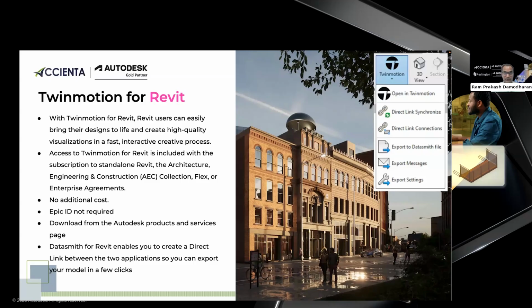So for example, if you're using it, Cholin, you can correct me because you are the power user who uses Twinmotion, and I just have some insights from you. That's my real experience, which I discovered: when I use Revit 2024, Twinmotion 2024 is not the equivalent one. Then I discovered that Twinmotion 2023 should be the right one. So if anybody had the same experience, you can share your insights so we can have better clarity on it.